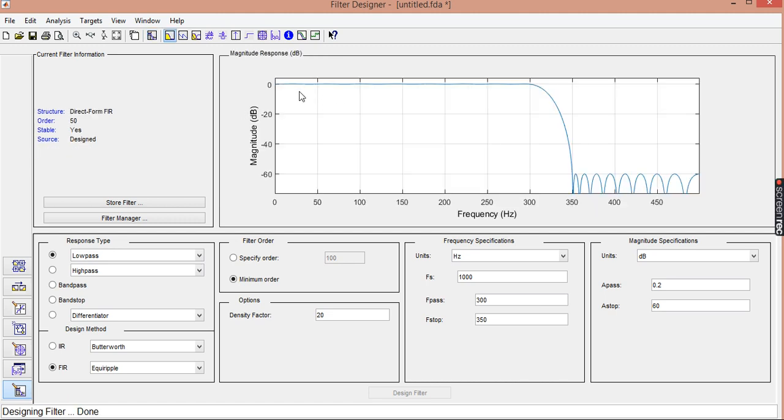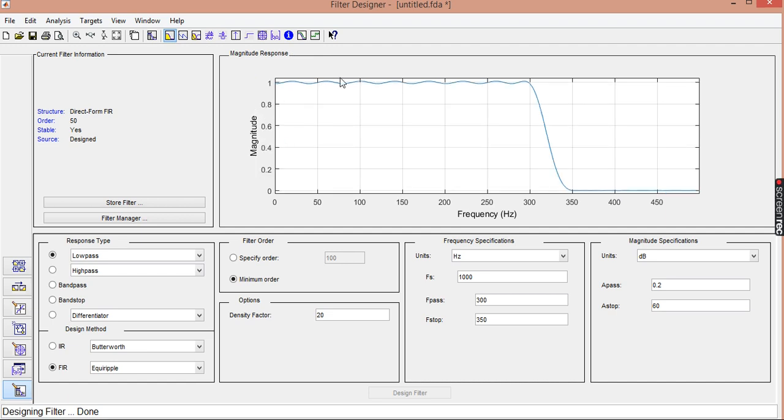Okay, here's the magnitude response in decibels. If you right click on the vertical axis and select magnitude, you can see those equiripples because we selected the equiripple design. So in the pass band we have the maxima reaching equal amplitude, minima reaching equal. So these are equiripples in the pass band. Then in the stop band we had at least minus 60 decibels of attenuation starting at 350, and we were interested in having frequencies up until 200, and we were supposed to reject 400. Okay, so 400 is not desired.